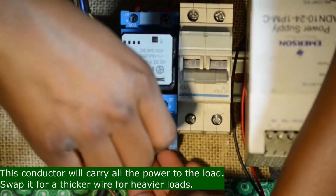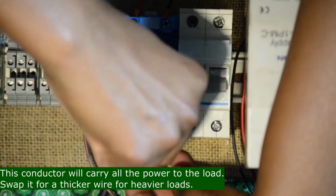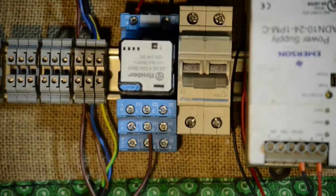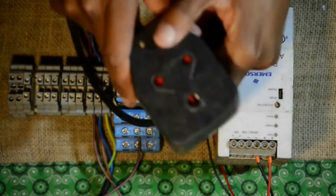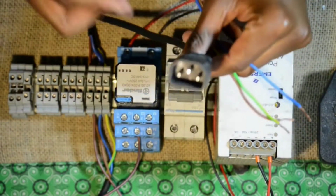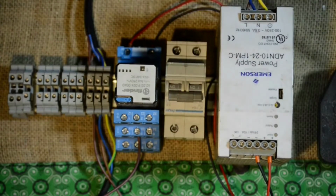So what this means is that if it's in the normally open, it means that when the system is entirely off, the normally open contact does not make any contact. It's normally open. And then when we actually switch the power on, because it was open, it actually closes. And the one that is normally closed now becomes open. So that's how it basically works.